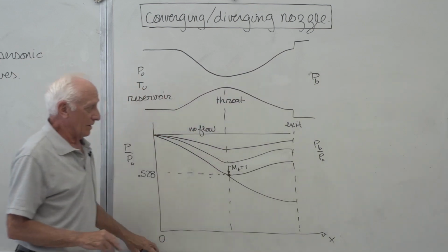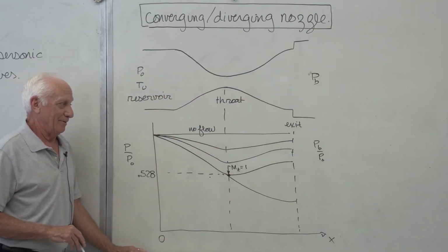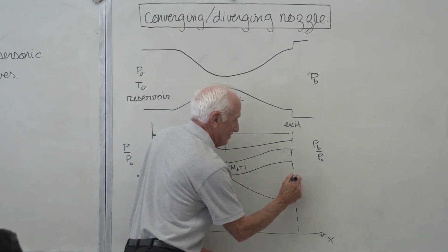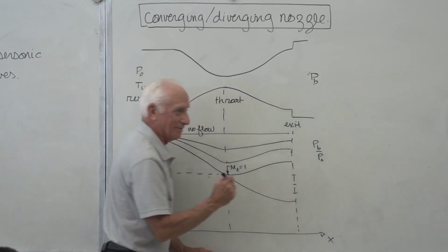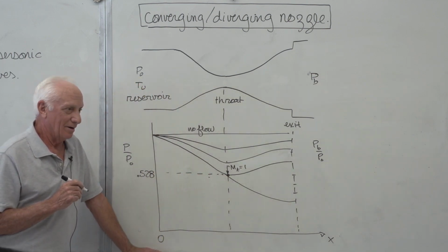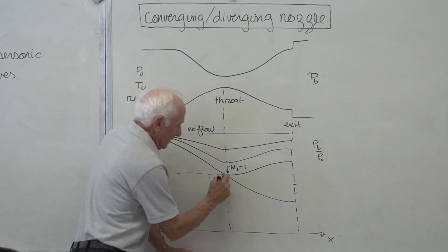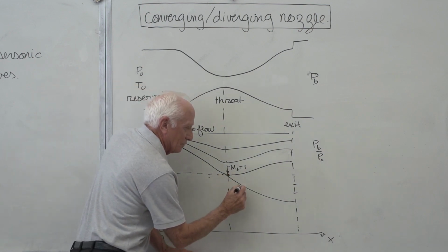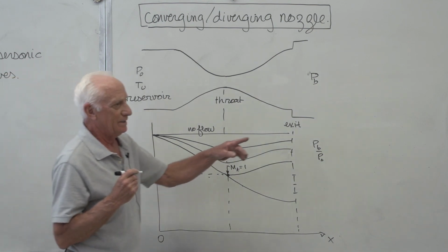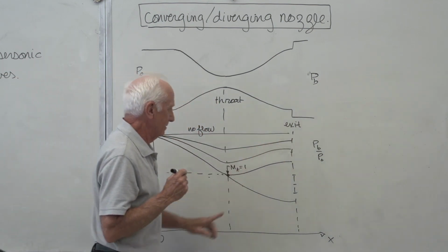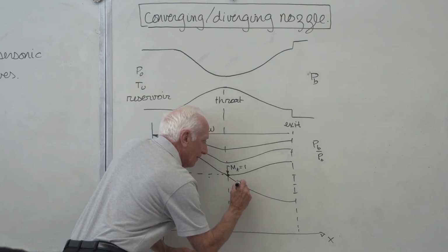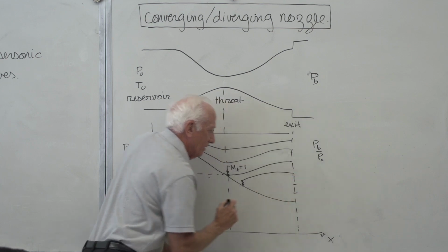And we stopped there last time. We said, okay, there's a big gray area there. We don't know what's going on there. What if the pressure is here? Any of those little tick marks on there? What happens there? Okay, here comes the shocks. You go through Mach 1, the flow becomes supersonic. Could there be a shock? Yeah, there can be a shock because a shock has to occur in supersonic flow. So what happens is there's a shock there, and it goes back to there.